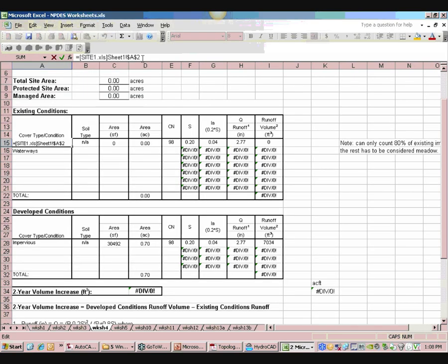And there's a little trick in Excel, if you take these dollar signs out of the front of both of these, you can highlight the rows, press Control and hit R, and it will, what do they call that, fill right.